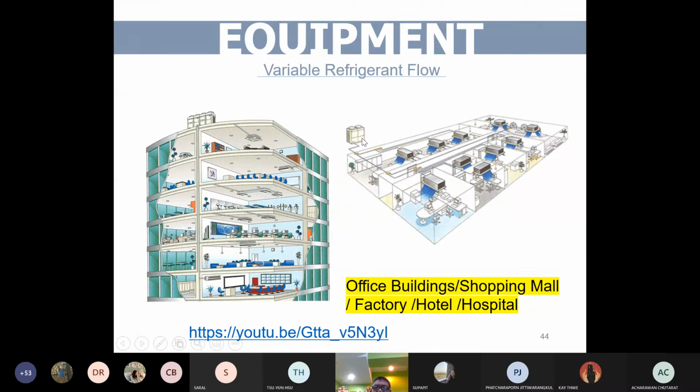Field module of the condensing unit can hook up with the multiple fan coil in the area. So in some cases, they did not need the load, so they can share the load together in this area. So the VRF system will be part load, and currently all VRF brands have the inverter already, so the power consumption is even better than the air cool chiller in many cases.